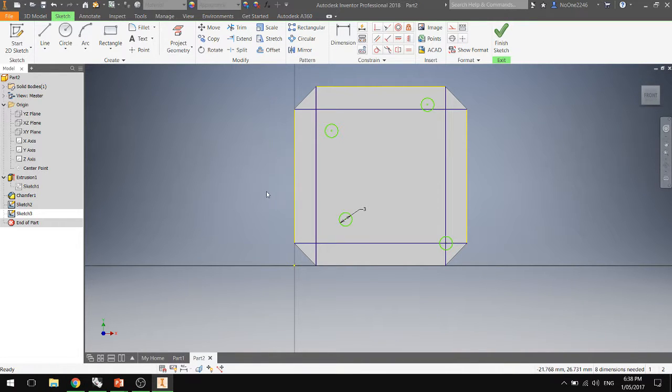The name of the tool? I'm just clicking. Do you want to lock trace over to? Actually, all I'm trying to do is make it like. Yeah. You can't make coincident constraints in 2 separate sketches. You can, however, trace over the previous line and create it as construction. That's what I was trying to do. So this is why I don't use this. So what you want to do is, just go to the other one. Just delete this sketch.